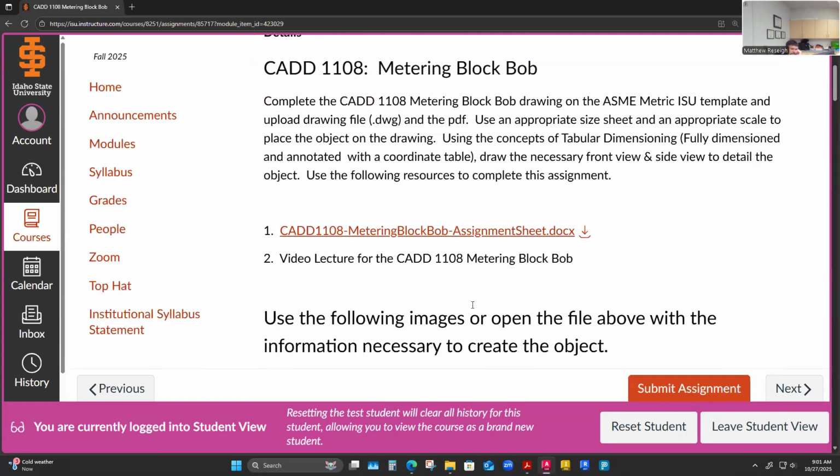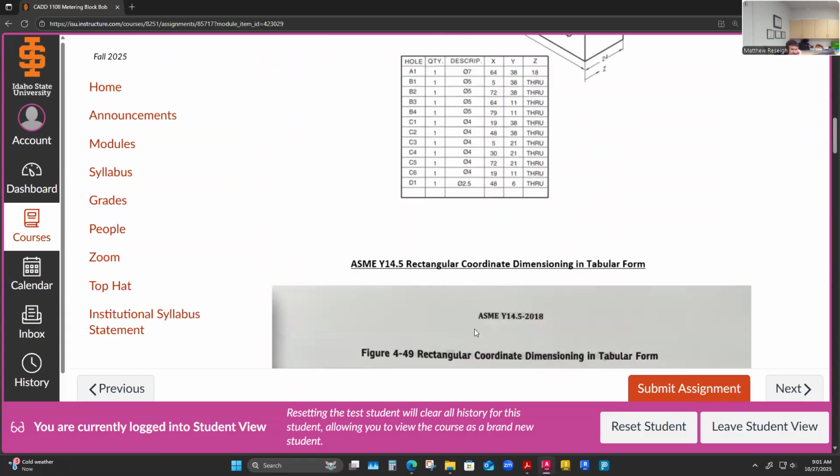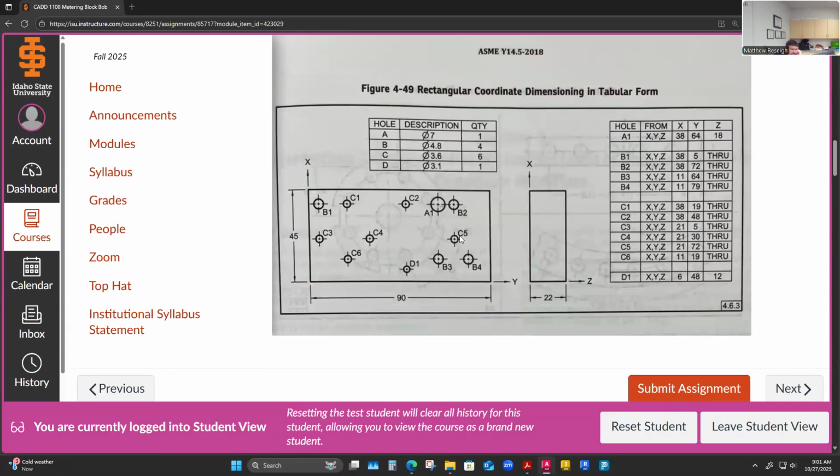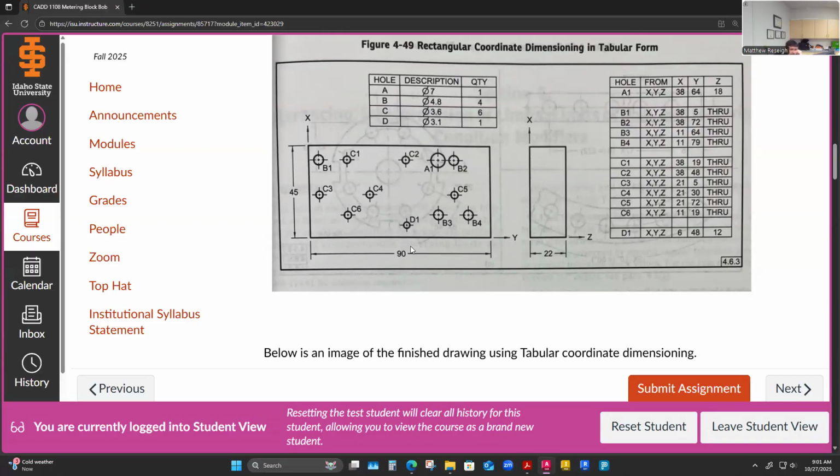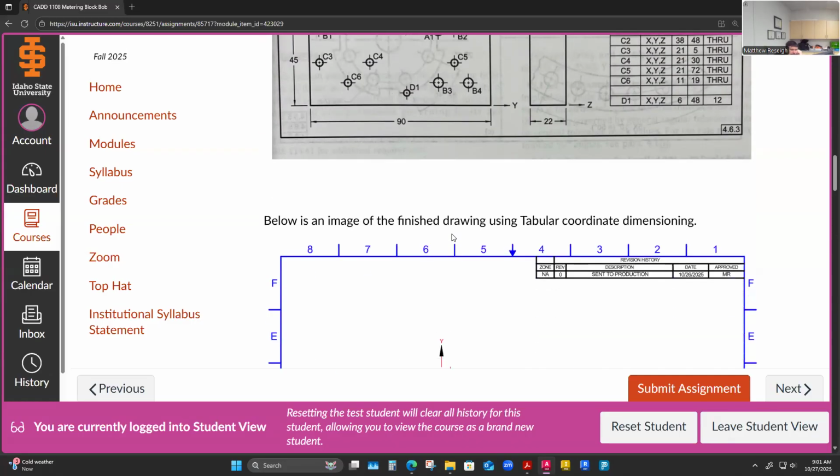Here's another rule that you can kind of break: you actually get to place the feature label on the actual part. It doesn't have to be a leader line pointing to it, but it could be that too. Somebody could have decided to do their feature labels with leader lines. In this case, we're just dropping multi-line text boxes close to my feature, in no particular orientation around the feature. It looks like they're mostly upper right, lower right, upper right. Here's a lower left. So it's just wherever it looks clear. There's no right or wrong in where you place the feature label around the feature, I feel.